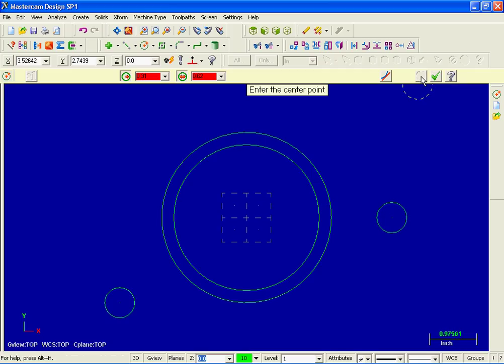Now for the next circle, we're going to put in the circles that have a radius of 0.75 and are at the center of this 0.62 circle on the right and this 0.62 circle on the left. So let's move up to the ribbon bar, and I'm going to click in the white space, and for the radius input 0.75, enter, and I'm also going to click on the radius icon to lock them in.